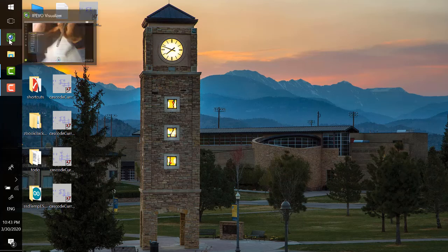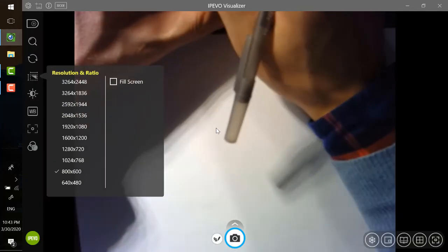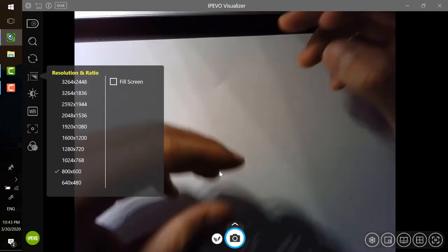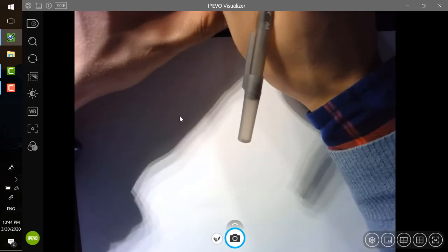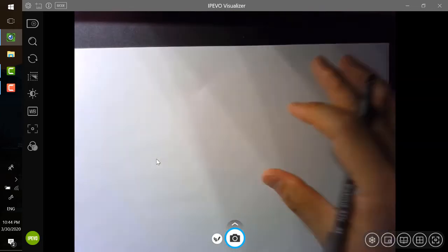Right, so in this lecture, we're going to introduce the cascoding current mirrors, because by putting all these NMOS together one by one, just on top of each other, it's going to increase the output resistance of the current mirror's output stage, which is pretty useful. Right, so now let's see how we can design this.